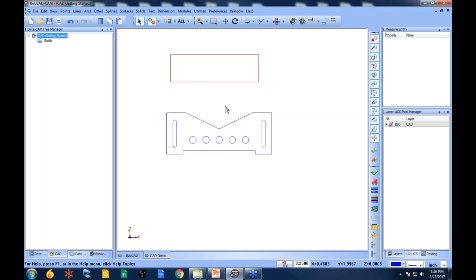What I would generally do from there is move that geometry to its own layer. Then I can turn that layer off, and that will show me that there was other geometry underneath it. So instead of using window selection, use chain selection for your chains, and it will eliminate the problems that you get with window selection or color selection on profiles for profiling and pocketing. So hopefully that answers your question there.